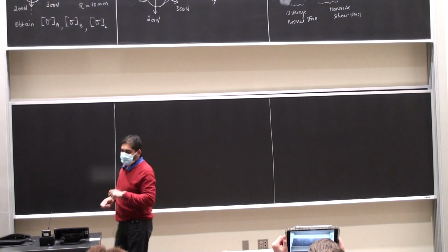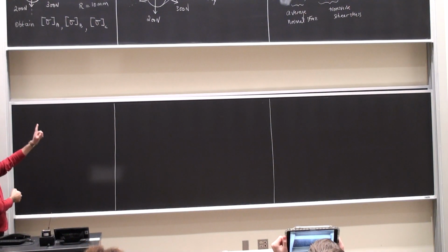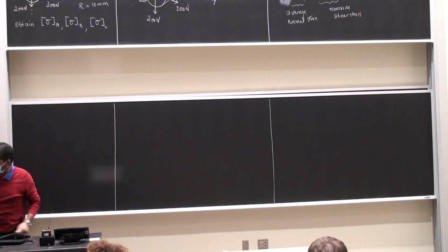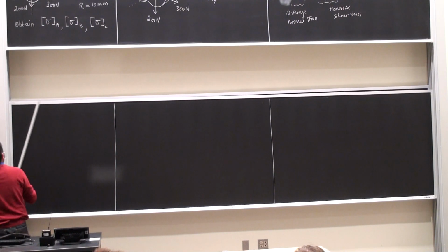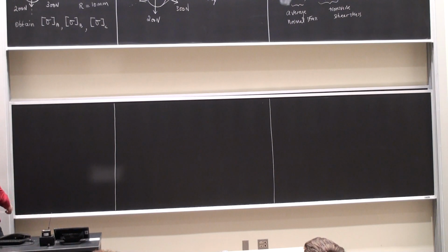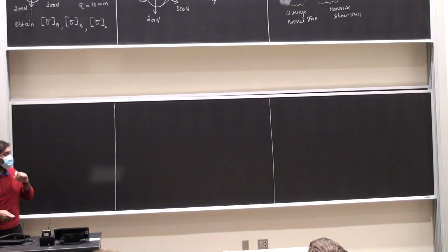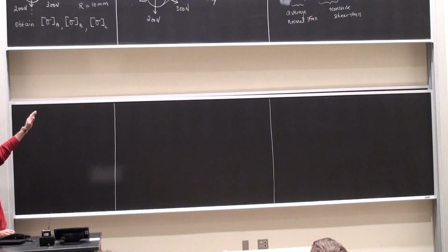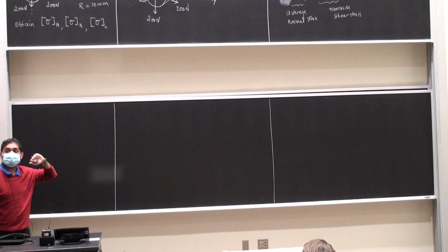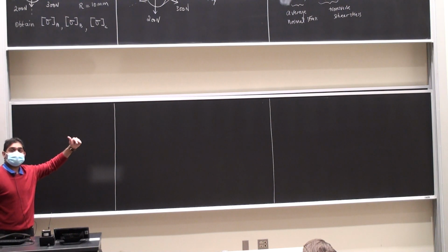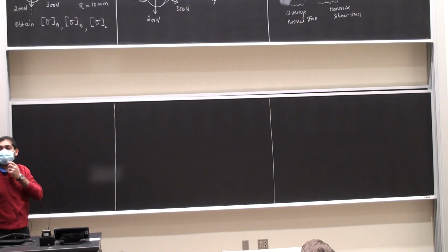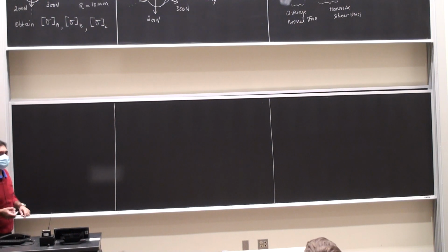Alright. I'm not going to draw the figure again, but maybe I need that figure down here for the moment mapping, so I'll pull that down in a minute. But force balance is fairly easy. You can just visually recognize that Vy is going to be equal to 200 newtons, Vz is going to be equal to minus 300, and Nx is equal to 0. But we will still do this carefully.